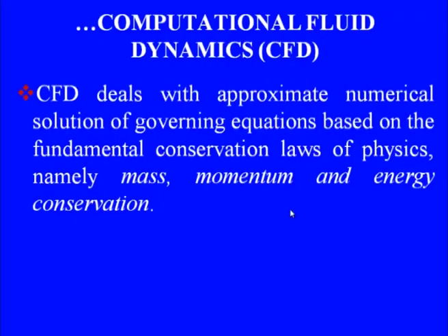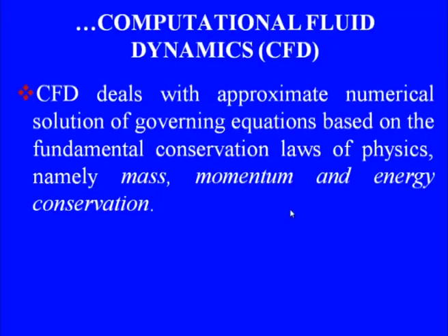Now what do we do in computational fluid dynamics? We basically try to find approximate numerical solutions of governing equations of flow problems based on fundamental conservation laws of physics, namely mass, momentum and energy conservation. So, there are three laws based on which we would obtain the mathematical model of a problem, and we would solve it approximately using digital computers to obtain the solution of a problem.